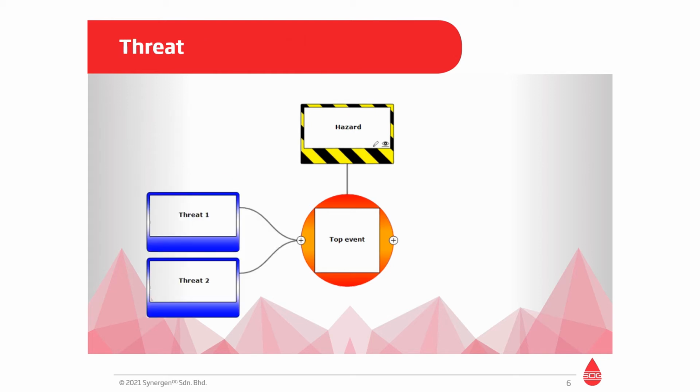The next step in the bow tie methodology is to think of ways in which this top event can occur. What can cause a top event? These are termed threats. Things to keep in mind are that threats should be direct and independent, for example, corrosion, material fatigue, mechanical failure. It is something we protect ourselves against by implementing barriers. It should be noted that barrier failures are not threats. For example, inspection not done is not a threat but a barrier failure. Inspections are barriers in place that prevent threats from leading to a top event.